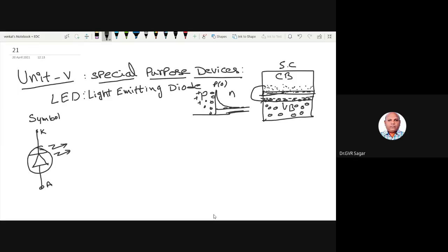Each hole is not a simple hole, is it not? A covalent bond is there, then a hole, then an electron. Electron indicates negative charge, hole indicates positive charge. This is the electron-hole pair again. So each hole represents an electron-hole pair.